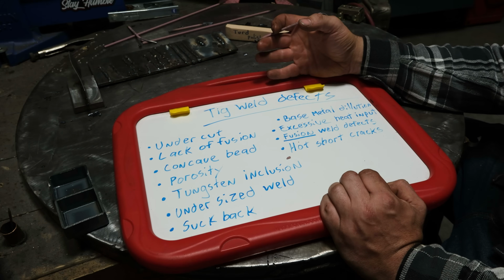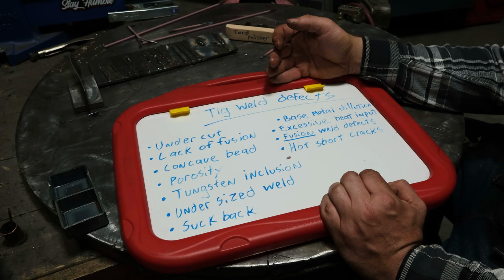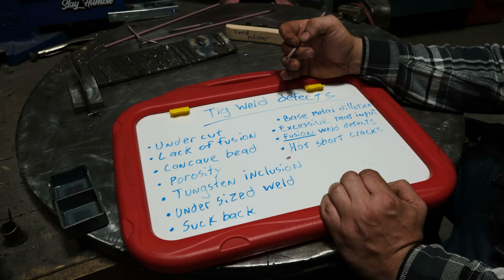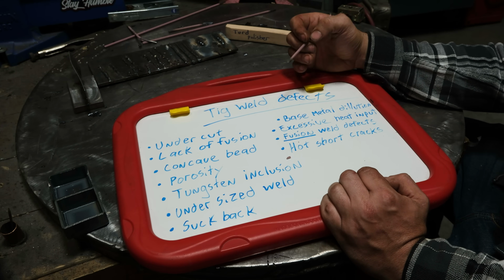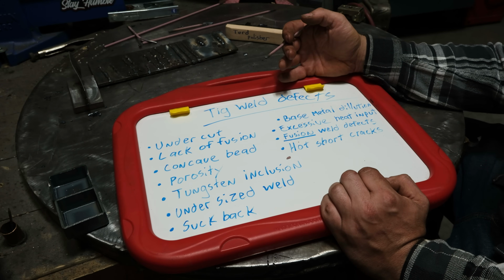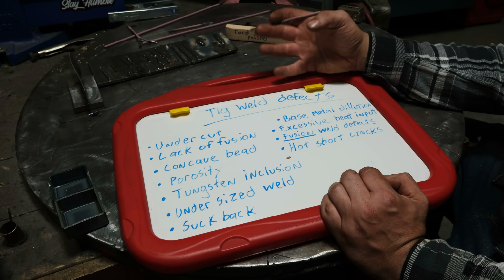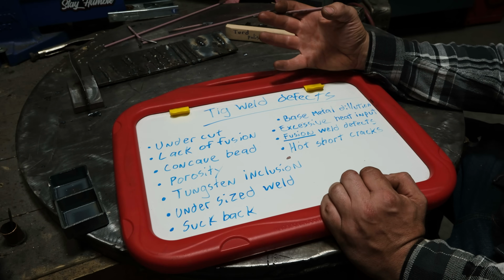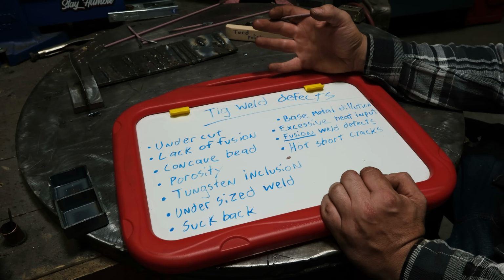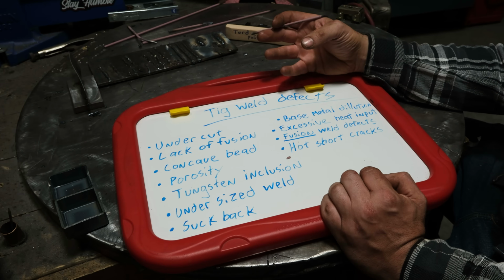So even if you do a crappy root with not enough reinforcement on those, and then you go back over and re-weld it, the root pass is probably highly suspect. So you always want to push enough filler material into the weld to where you are mixing an alloy. You have an alloy of basically your base material and the filler rod. You don't want, on any kind of material realistically other than mild steel, to just have the base material melting and trying to use that as filler.